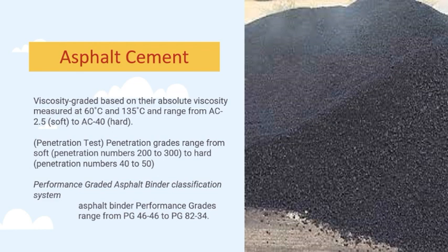So next natin is about asphalt cement. Solid form of asphalt. Obviously, asphalt should be heated to get to its liquid state and be used in bituminous mixes. Traditionally, viscosity graded based on the absolute viscosity measured at 60 degrees and 135 degrees and ranges from AC-2.5, which is soft, to AC-40, which is hard. So meron ding isa pang alternative test, which is yung penetration test na nagre-range from 200 to 300 for soft, to hard penetration numbers 40 to 50.